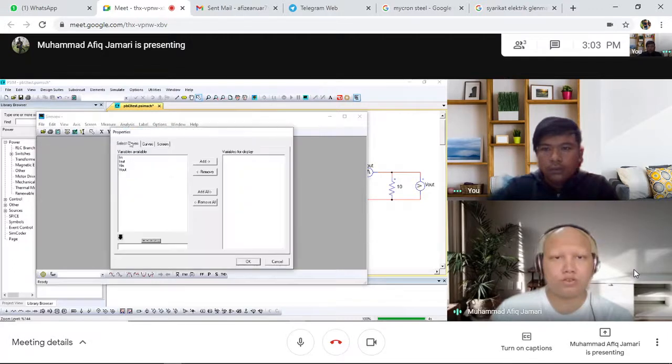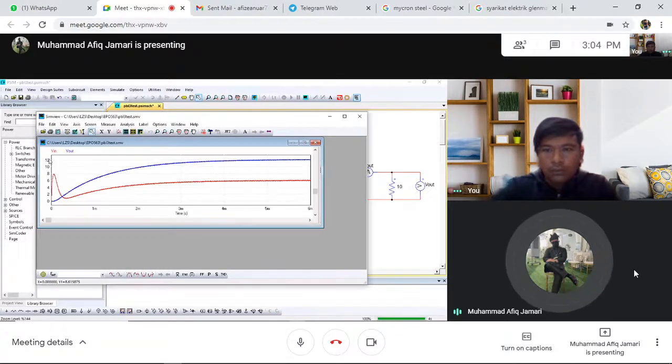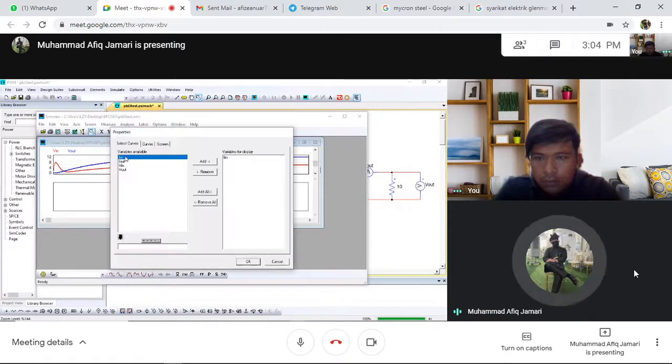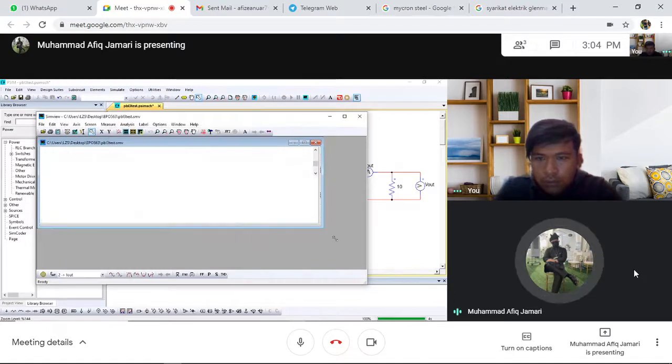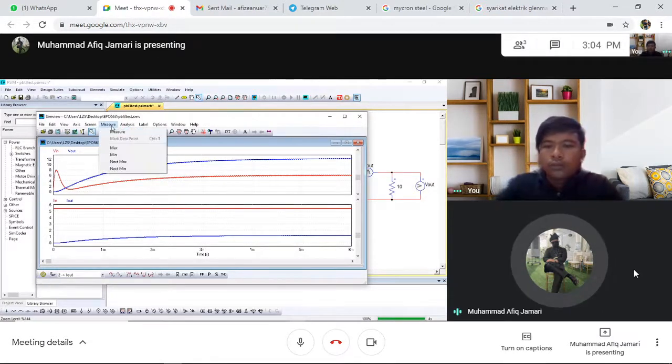So this is the output result that we are going to watch. First we click V in and V out. This is the waveform, which you can see is a constant 12 volt for our V out. Now is the I out. This is our current, V in, V out, and I in, I out. We get the amounts that we need for the table by clicking measure.